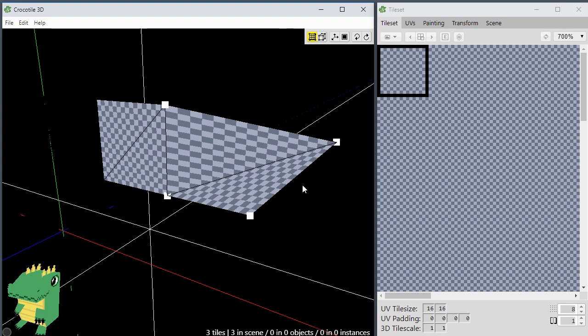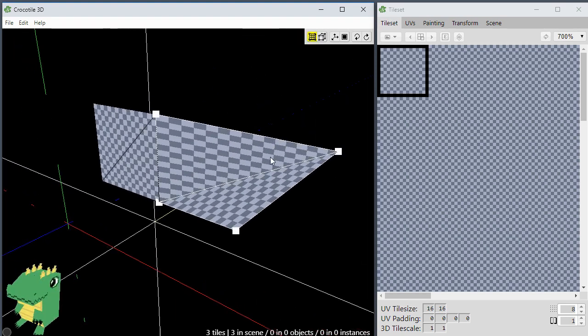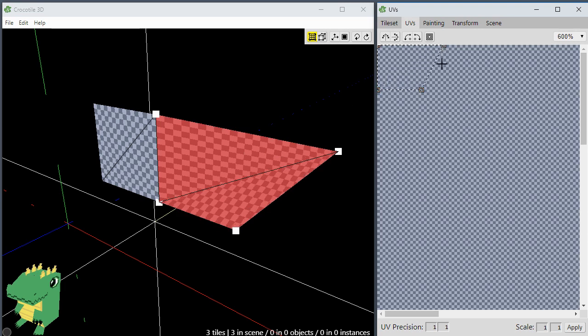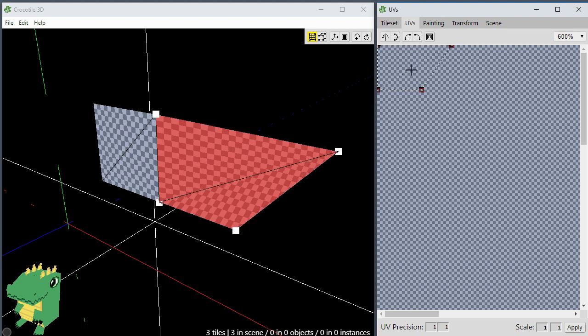Then when you adjust the UVs of the tiles by clicking on a tile, then going into the UV editor, here's the UV being displayed on the tile set. You can adjust the UVs like so to fix the stretched pixels if you want. And by having a checkered pattern there, you could see how your changes to the UVs display the texture in different ways.